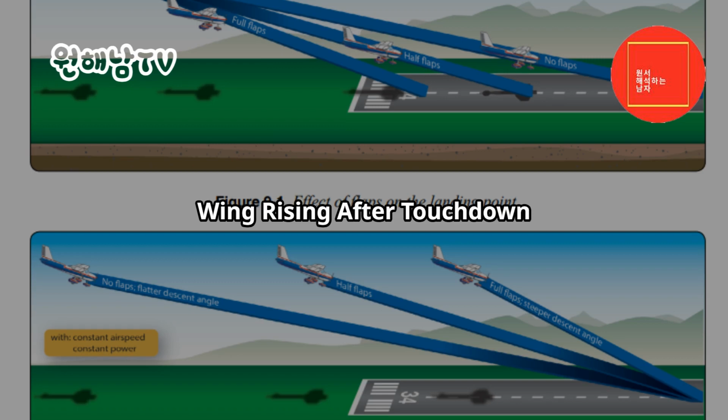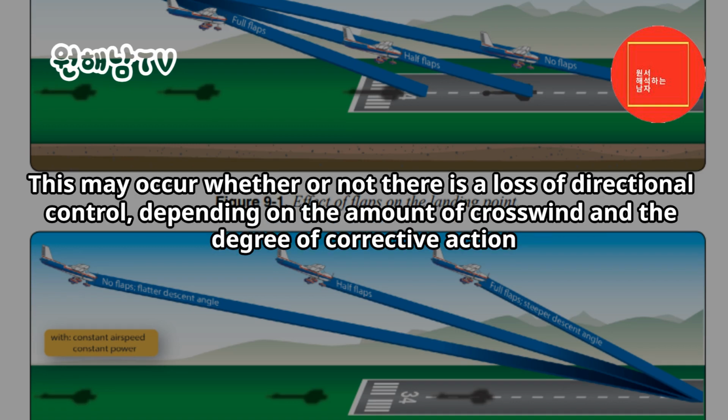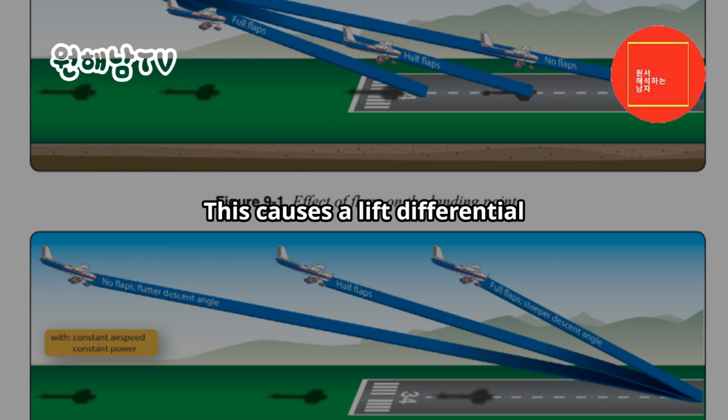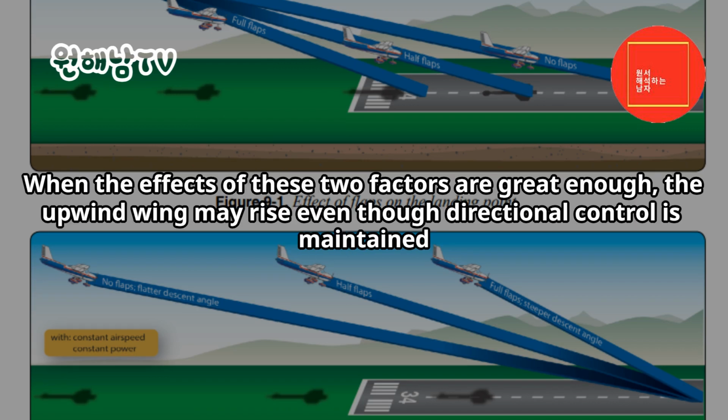Wing rising after touchdown. When landing in a crosswind, there may be instances when a wing rises during the after-landing roll. This may occur whether or not there is a loss of directional control, depending on the amount of crosswind and the degree of corrective action. Anytime an airplane is rolling on the ground in a crosswind condition, the upwind wing is receiving a greater force from the wind than the downwind wing. This causes a lift differential. Also, as the upwind wing rises, there is an increase in the AOA, which increases lift on the upwind wing, rolling the airplane downwind. When the effects of these two factors are great enough, the upwind wing may rise even though directional control is maintained.